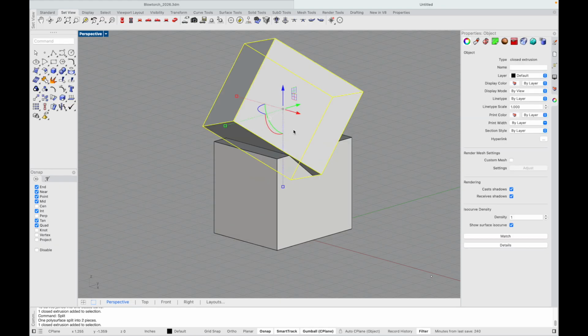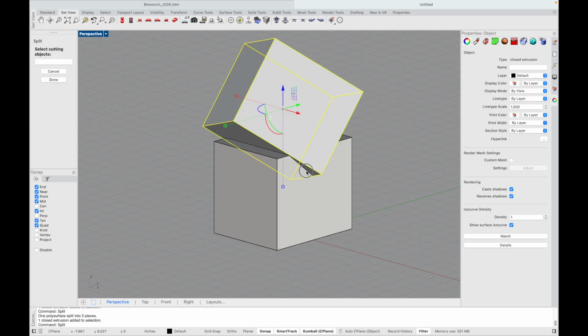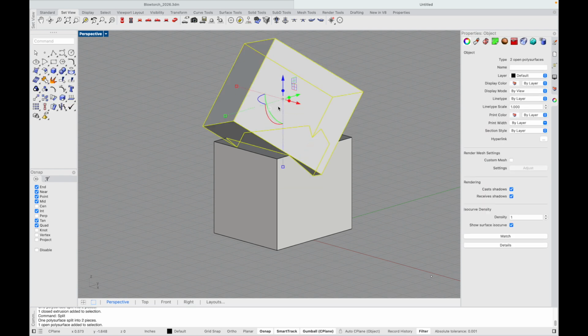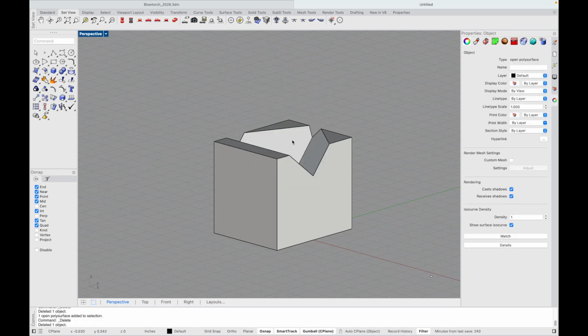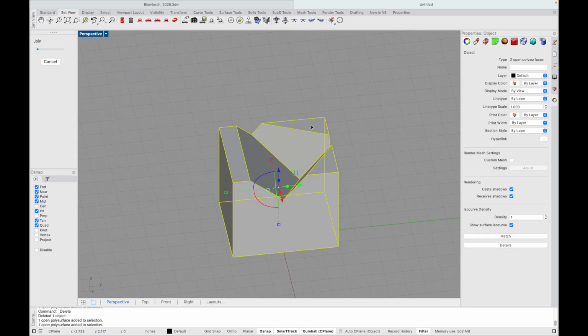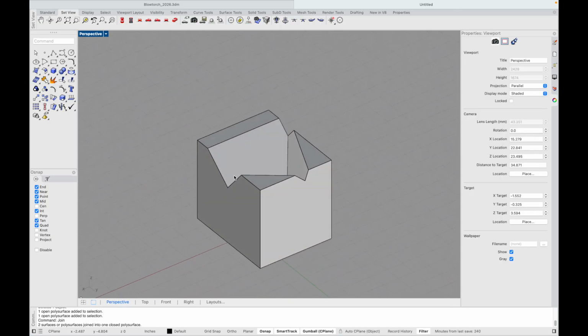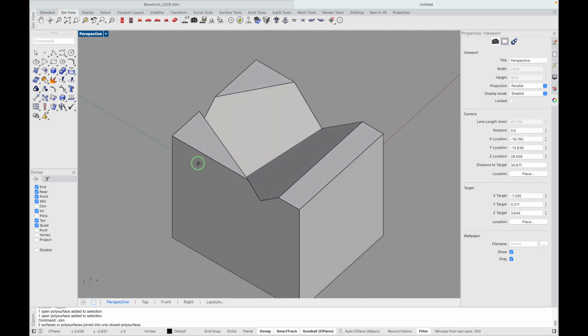And then I split the other one here with the same curve, which should work because this curve should perfectly intersect both of these, done. And I can say delete this, then delete this, then this surface got cut off of that one, join it. And now I've got a closed model that has that thing cut out of it.